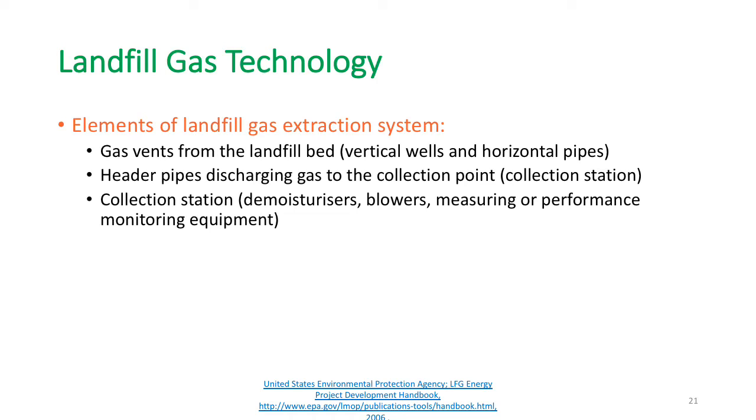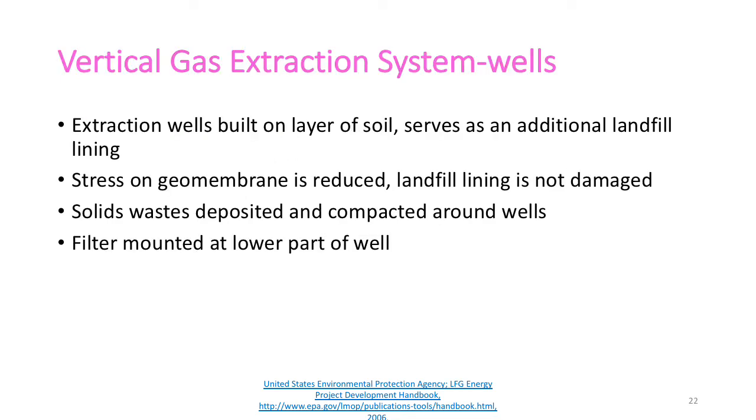Moving on to landfill gas technology. Landfill gas is collected by various extraction systems like gas vents from the landfill bed, vertical wells, and horizontal pipes, header pipes discharging gas to the collection point, and collection station that is demoisturizers, blowers, measuring or performance monitoring equipments. There are some of the elements of installation for gas extraction.